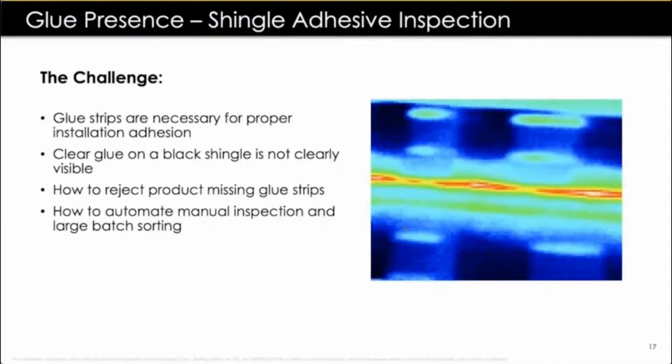I don't want to say it looks like a snake when you see how fast this is going down the line, but you want to have that dynamic movement of the region of interest, or the specific area of interest, and then doing those calculations. And these camera calculations, by the way, calculate in about 0.8 of a second. So on a frame rate, we're only catching every fifth batch of shingles coming down. So decision making again had to be very quick, even processing at about 0.8 of a second.